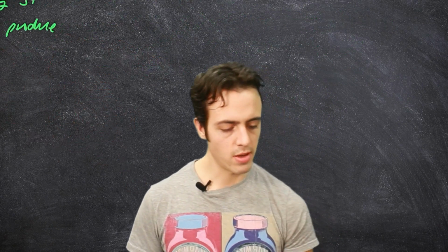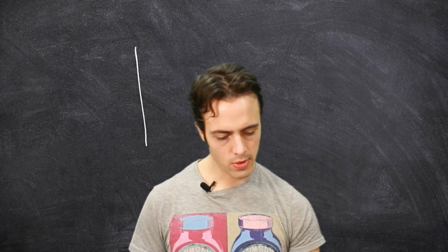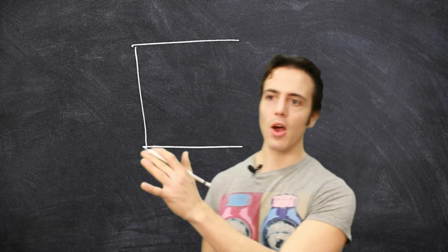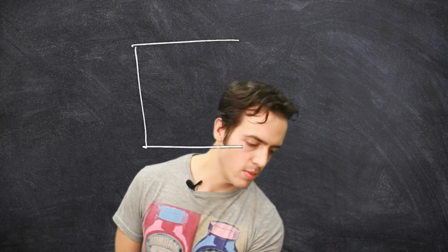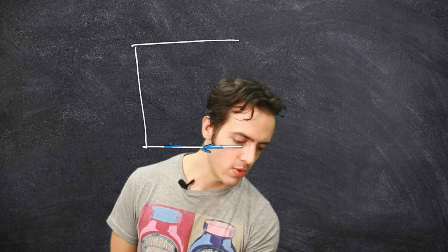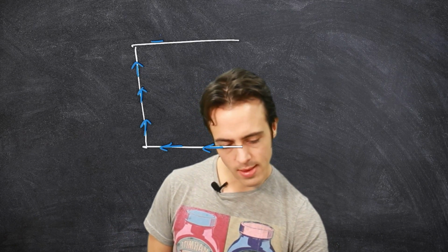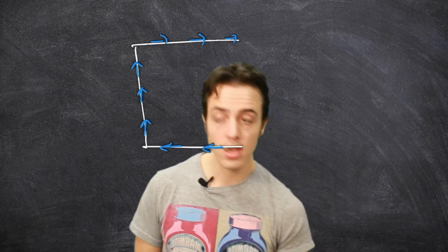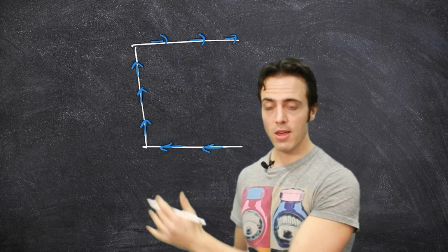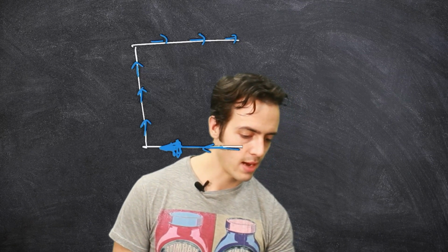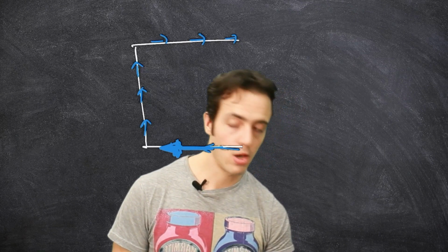If we're uncertain about why, let's just remind ourselves exactly what these shear flows are. Even though I draw the arrows next to them, we've got to remember that shear flow is newtons per meter acting along in this direction. So when I integrate these to produce a single force, it would just be a force acting somewhere along this body.